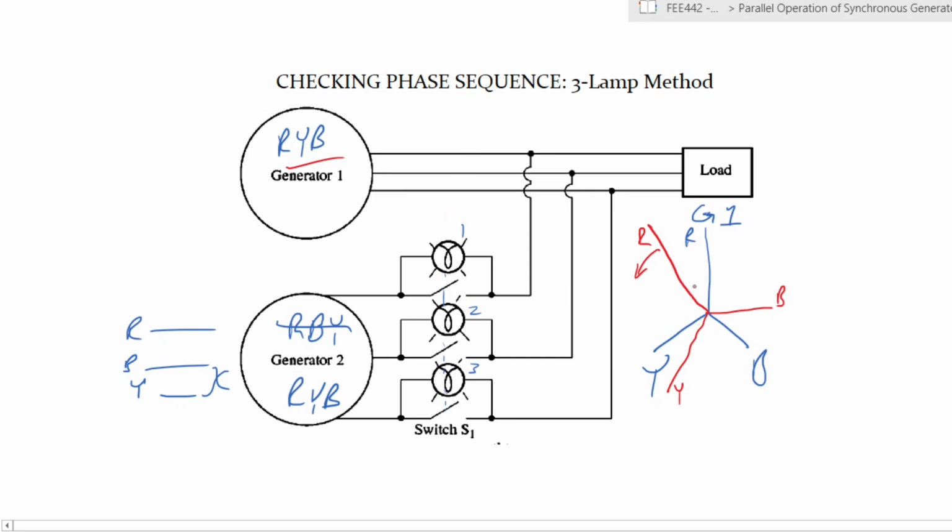That would mean, in terms of the phasors, if we assume generator 1 as the baseline, it would appear that either generator 2's phasor is moving away from generator 1 or it is moving slightly towards it. So if it is faster, it is moving away, say in an anti-clockwise direction. If it is slower, it is moving towards it, say in a clockwise direction.